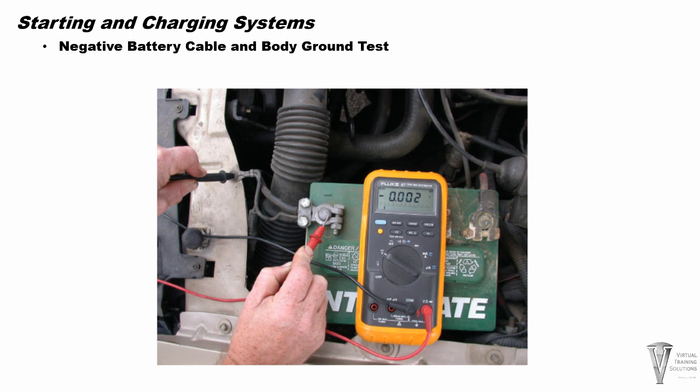Starter ground circuit current can destroy throttle cables, transmission floor shifter cables, clutch cables, emergency brake cables, and speedometer cables. This current can also damage transmission bearings and driveline U-joints. A scorched or burnt ground wire between the battery and the body and the negative battery terminal is a telltale sign that someone forgot to tighten up the negative battery cable to engine connection.